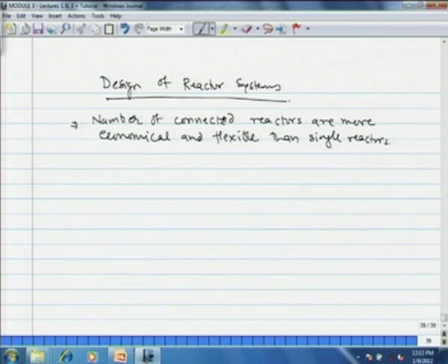The reactor combination or arrangement for optimal production of a product is subject of analysis. The criteria is same as for single reactor with added issue of arrangement of these reactors. So if you want to split one CSTR into three CSTRs, then you have to adjust the intermediate compositions properly so as to have the same overall conversion as in case of a single CSTR.